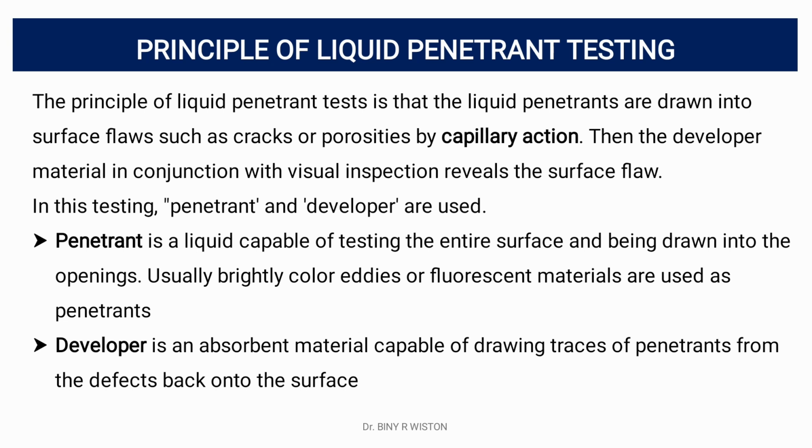The ability of a given liquid to flow over a surface or enter surface cavities through the mechanism called capillary action is utilized in liquid penetrant testing. So, the developer material in conjunction with visual inspection reveals the surface flaws.